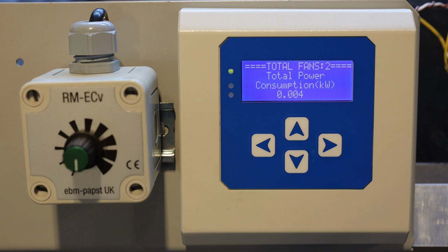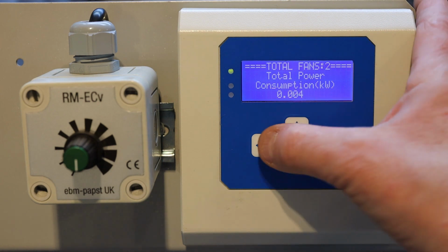In monitor and control mode, we can control the fan array via the MDC controller using multiple control inputs. By changing the configuration to respond to multiple control inputs, the controller will change the speed of the fans in the array according to the latest instruction received. Returning to the operation mode via the main menu, we can select Monitor and Control.